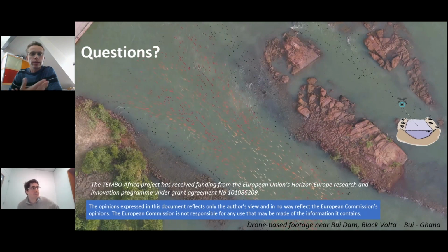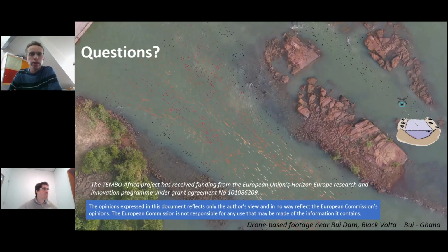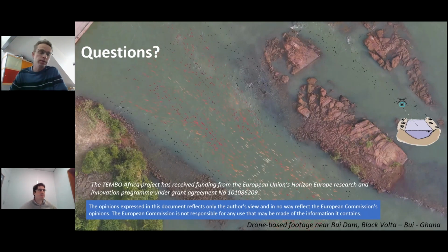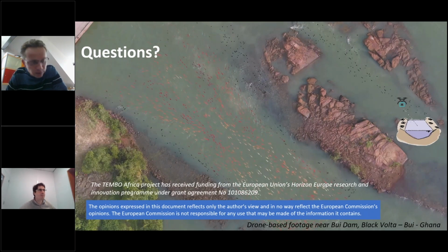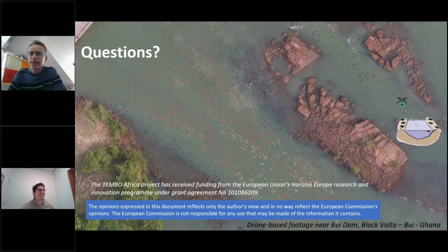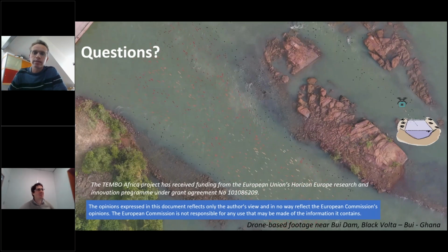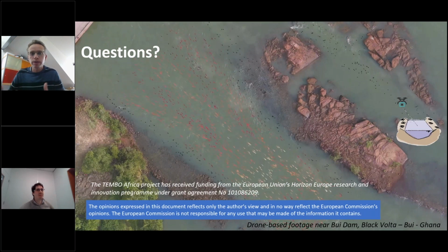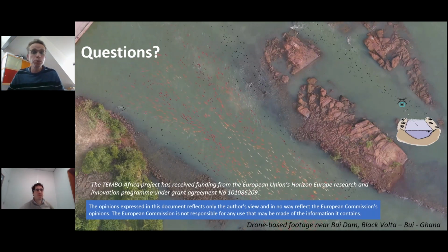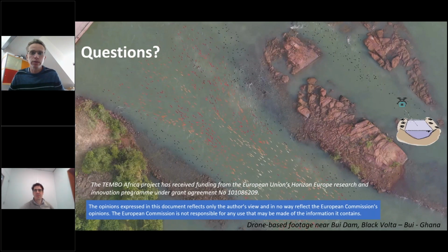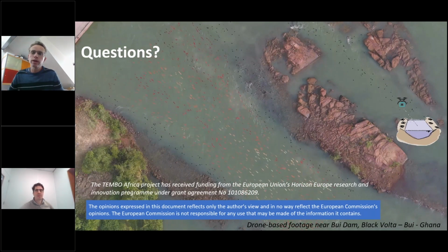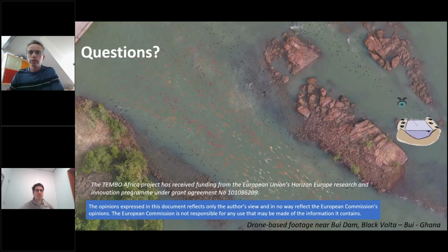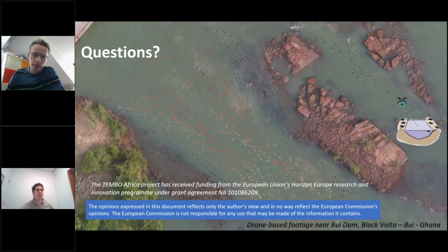And there's guidance and methods available in the documentation. Documentation is also key for good open source software, and I have to say that I spend a lot of time on documentation. So make sure that you have a look at that and really check: is my noise suppressed enough to warrant that I don't get spurious velocities that are not meaningful? A velocity of 0, while there is actually a velocity, but simply you don't have a seeding density, has a strong negative influence on the quality of your results, obviously.